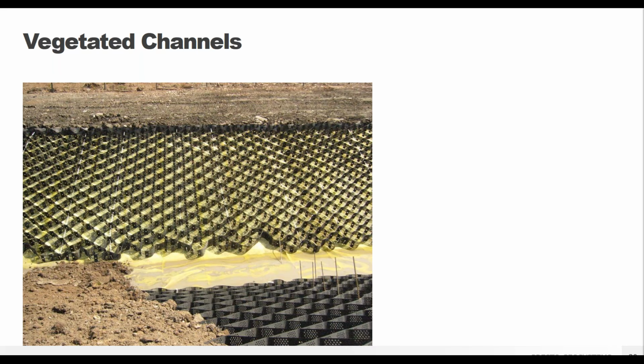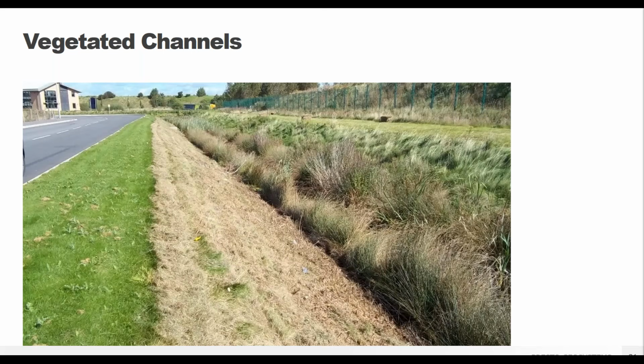You would just place the GEOWEB panels along the side slopes. So the panels will allow for that vegetation growth up both of these embankments, which normally might not necessarily be able to do underwater. And in this case, there was this bright yellow liner underneath the panels. So that's why they went with the tendon system. That way they wouldn't puncture through the liner and the GEOWEB panels would be anchored in place.